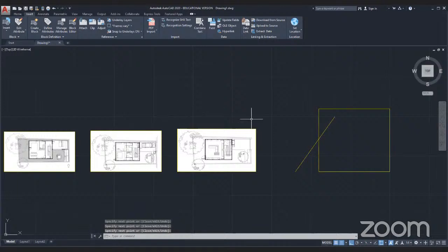If you got a straight edge building, whatever, all of your angles are true. Okay, we want to make sure that we always enter or escape to get out of the last command, because when you start typing, it'll automatically bring you into the last command that you entered. So I'm just erasing these things now.